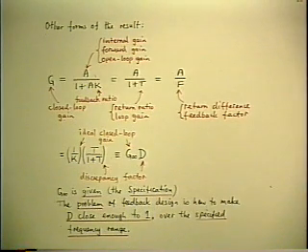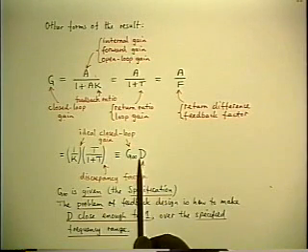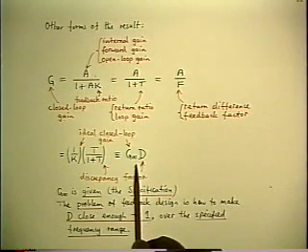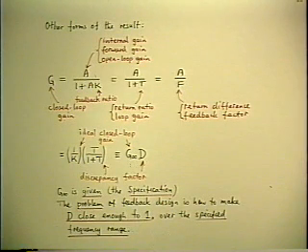But we're well prepared to deal with that now because we've already established the symmetry between the two directions of the frequency axis, which involves a horizontal reversal of all the diagrams to do with sketching the asymptotes, and it consists of simply inverting the frequency variable. Wherever you have an S for high frequencies, you have a 1 over S for low frequencies. So we've already set up the mechanism to deal with this problem at low frequencies once we know how to deal with it at high frequencies. It's just a symmetrical situation.